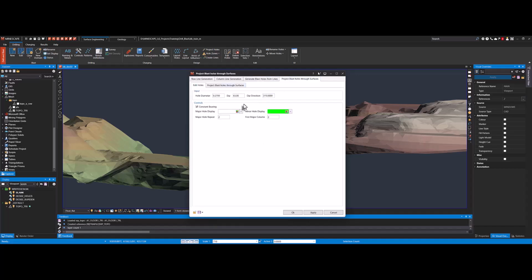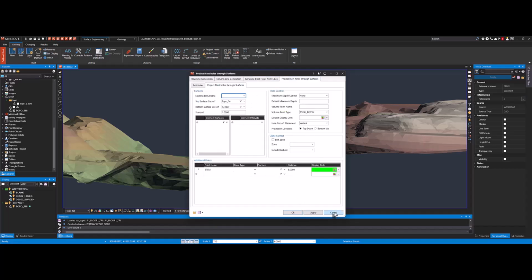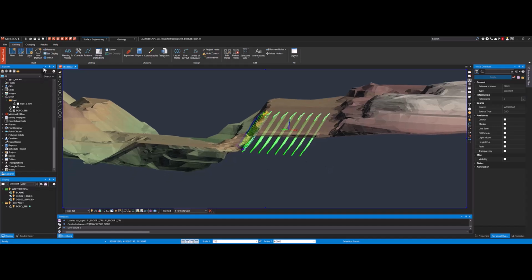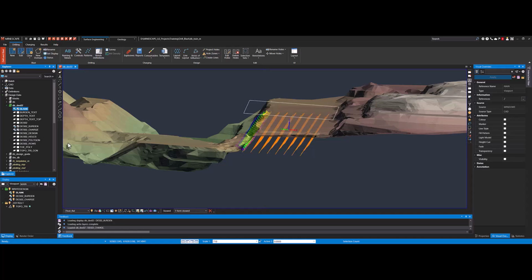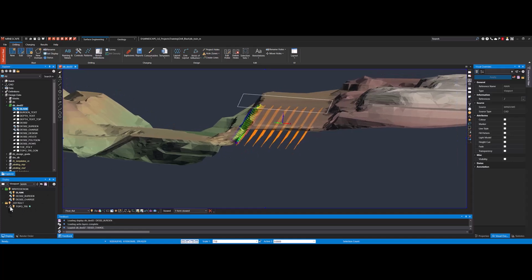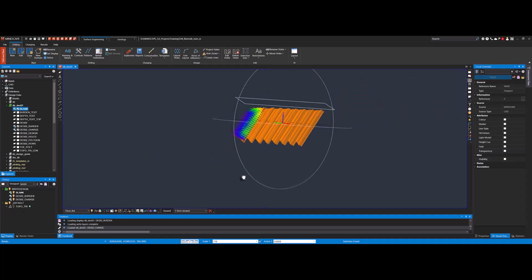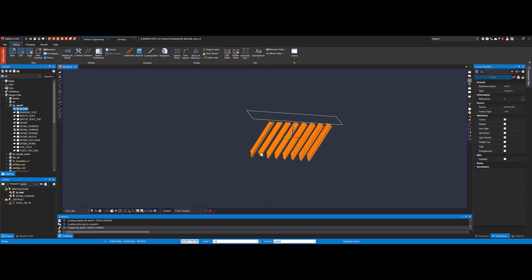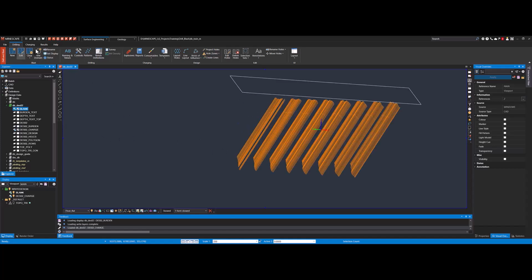That means you can refine timing sequences hole by hole until you get the exact outcome you want. The application also calculates all the key metrics: powder consumption, charge weights, and detonation timing tables. These are generated into detailed reports that can be used directly in the field or submitted for regulatory compliance. That ensures the blast designs are not only effective but also fully auditable.